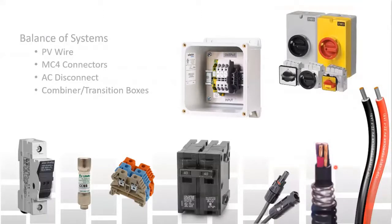Last part of the material side is the balance of system. So everything else is a typical distributor product. Outside, maybe what you see here, which is that PV photovoltaic cable rated for 2000 volts DC, also rated to be put directly onto the roof. And then some DC disconnects, AC disconnects are going to be common on the shelf. Everything else, tech cable, RW, conduits, breakers, fuse holders, terminal blocks, MC4 connectors, sorry, that's the only other one that you may want to add to your shelf if you're going to support the market.